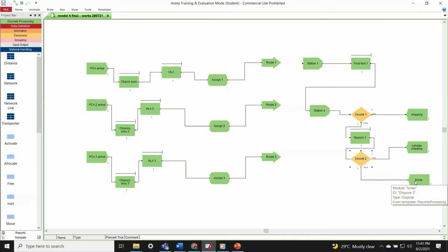We do not pursue rework 2. The reason is the sensitivity of this particular product, because it's quite sensitive in terms of the components. There are a lot of sensitive components being used in these RRH products, so we don't encourage moving to the next level of reworks. We want to make sure we maintain the reliability of the products once they are out to the customers.